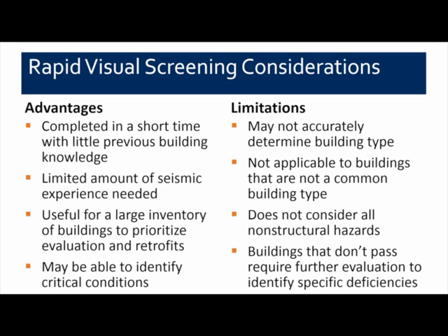So some of the advantages of using a rapid visual screening is that it can be completed in a very short time, and you don't have to have a lot of previous knowledge about the building. The form can also be done by somebody with very basic knowledge of seismic design. You don't have to have a lot of experience for that. And it's very useful when you're talking again about large inventories of buildings if you want to prioritize your further evaluations or retrofits. And these types of screenings can usually identify many of the critical vulnerabilities that Kelly discussed.